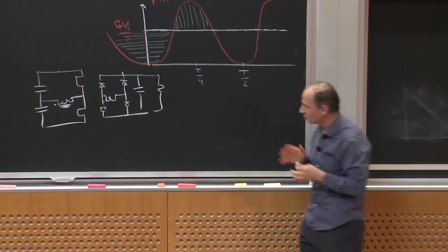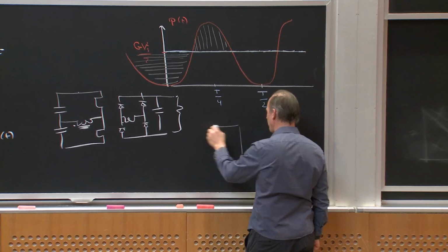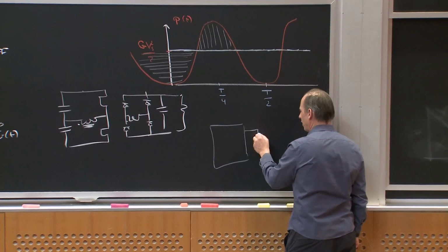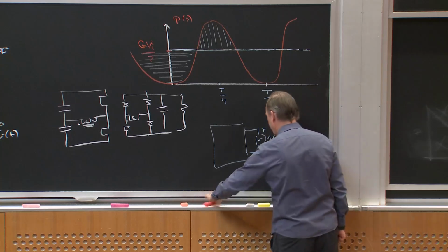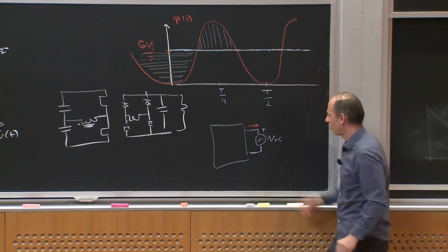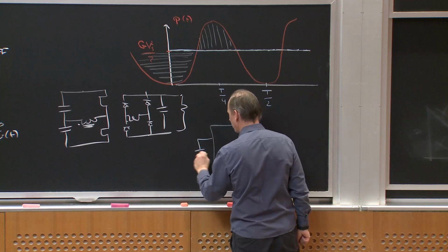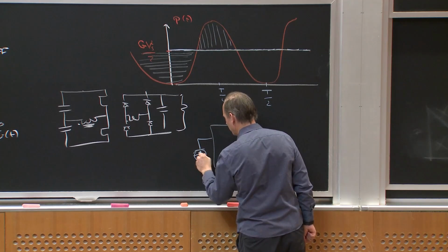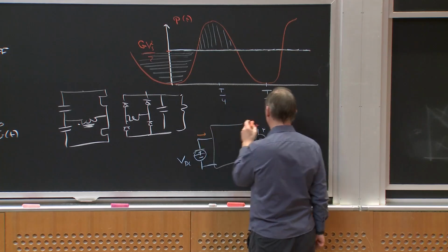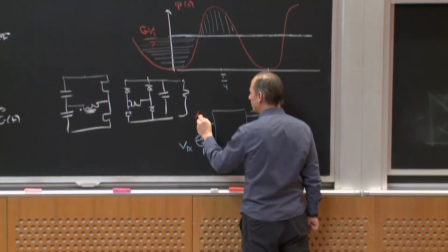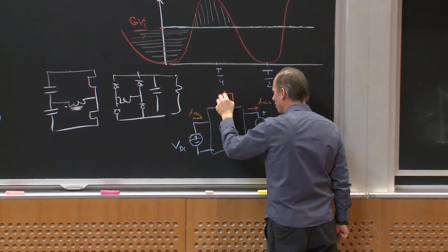So somewhere in your circuit, it doesn't have to be across the input or the output, but if you're going to have AC voltage and AC current on one side at unity power factor, and a DC voltage and a DC current on the other, so if this is IAC and this is IDC, somewhere in your circuit you either need an inductor or a capacitor.